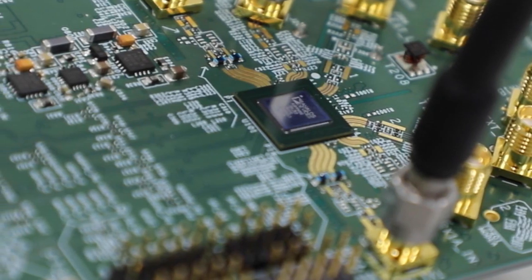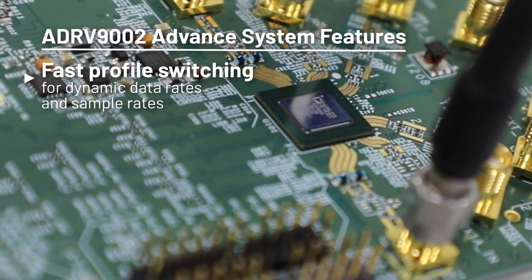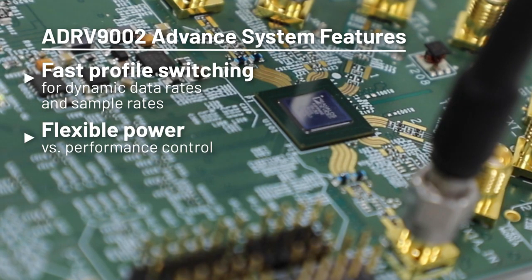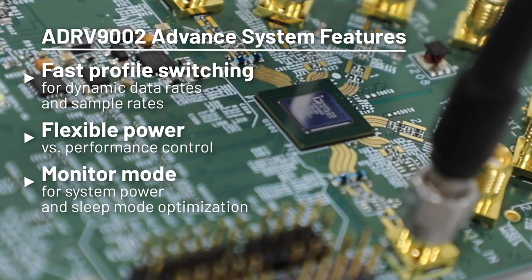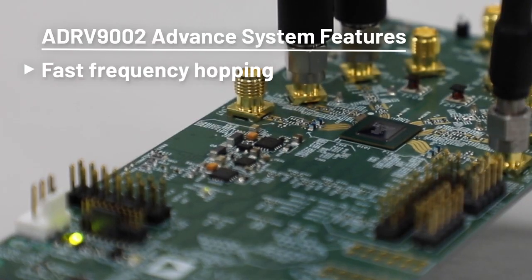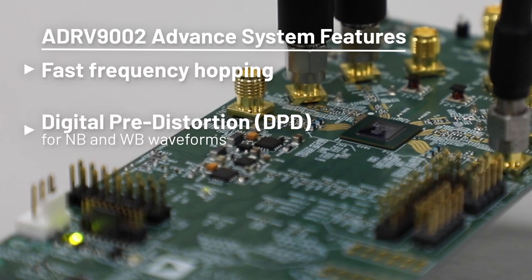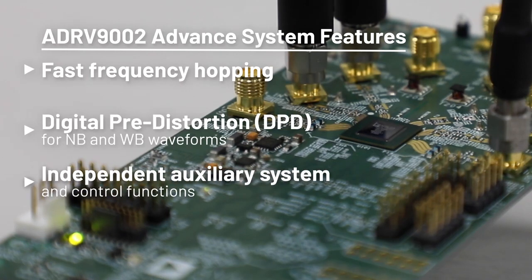ADRV9002 offers a number of advanced system features, such as fast profile switching for dynamic data rates and sample rates, flexible power versus performance control within the analog and digital circuits, a monitor mode for power and sleep mode optimization, multi-chip synchronization, fast frequency hopping, digital pre-distortion for narrowband and wideband waveforms, and independent auxiliary and control functions.